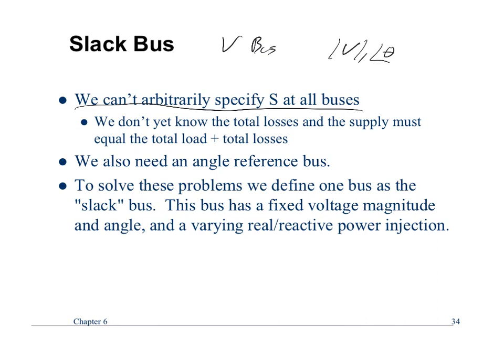But I don't know. I know in the real world, if you were to do an industrial system, like the University of Maine, you would pick the slack bus to be the utility connection, right? Because the Bangor Hydro connection can pick up as much power as necessary. We're always load, right? We don't have enough generation here to do it. So it's always a positive P coming into the system. But the Q and the P will go up or down. So usually when you're doing a load flow from a utility perspective, it's not a big deal.